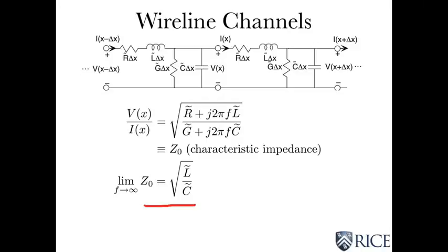I find it really kind of cool that the value of that resistor depends on the inductance per unit length and the capacitance per unit length. That's the way it all works out for this model, is that at high frequencies, the piece of coax, if you had to use a Thevenin equivalent, and you look down that piece of coax, at high frequencies it looks like a resistor.